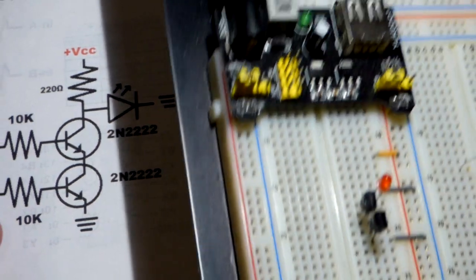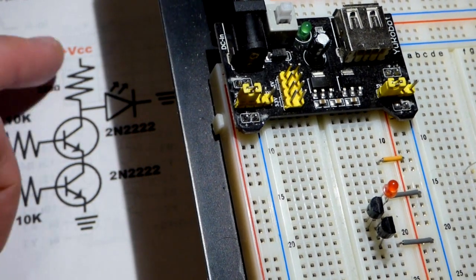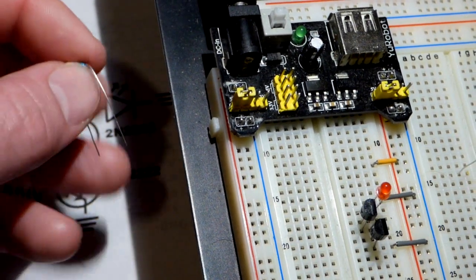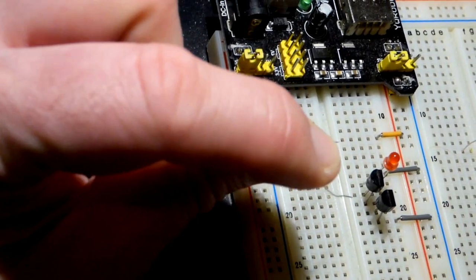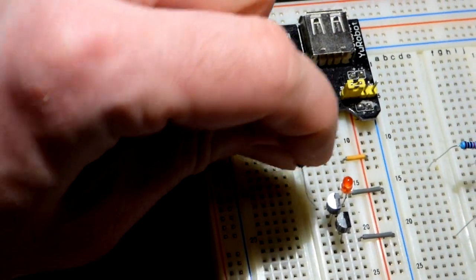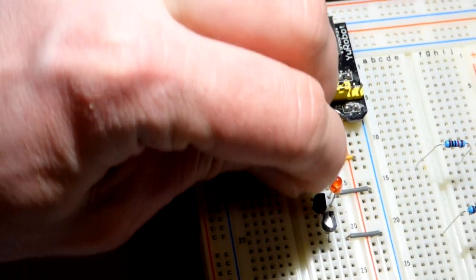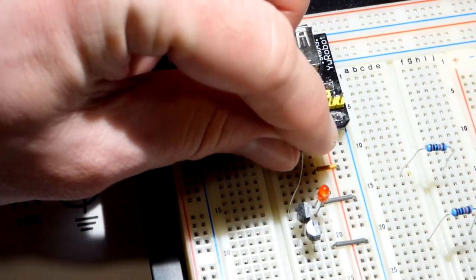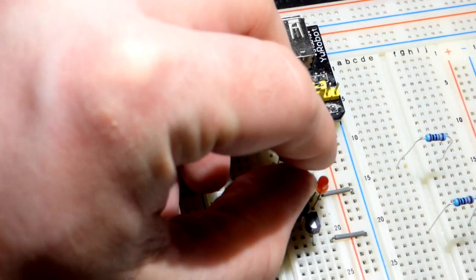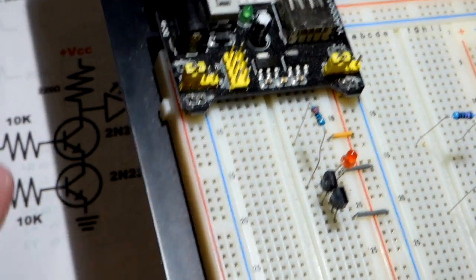So now, the other side, it's kind of the load, but we also have the resistor here. It's going to limit current through the LED and through the transistor. So 220 ohm, and we're going to put it where the collector here is, and then up here. Resistors are probably the most flexible components when it comes to a breadboard. And oddly enough, there we go. It didn't really want to go in that time. Hasn't been giving me problems yet, but there we go. You can see it's at the collector there.